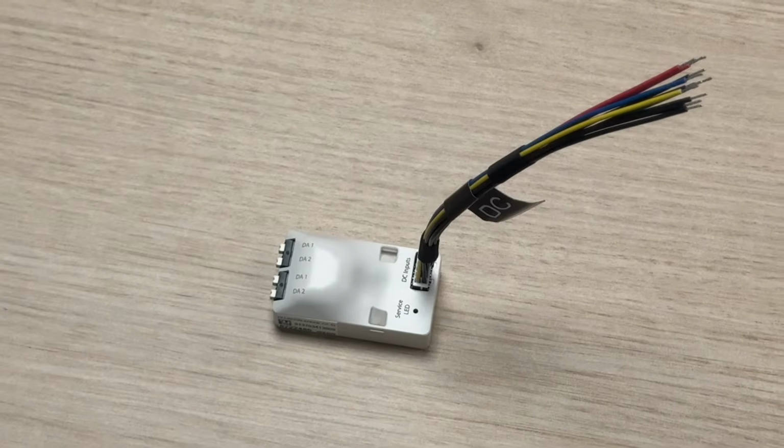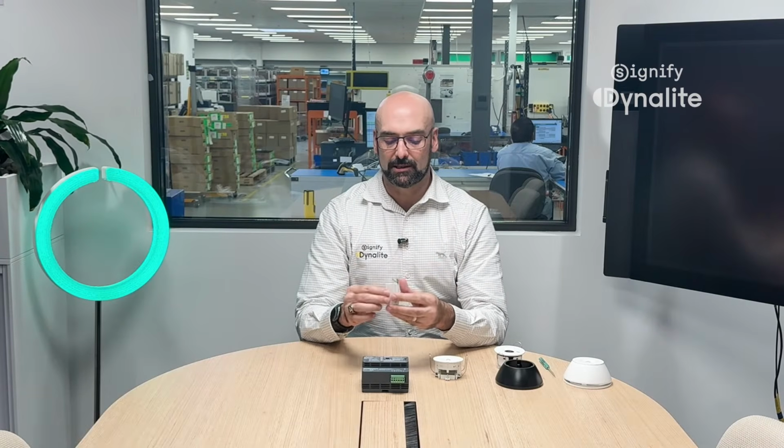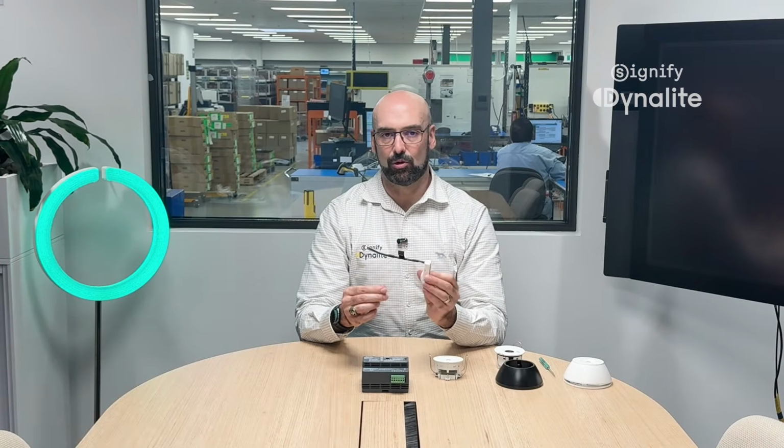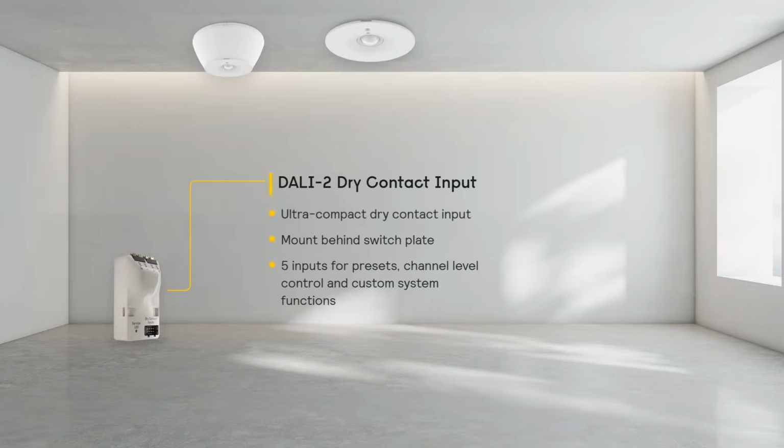Paired with this, we also have a new dry contact input interface. This is following the same mechanical design as we have for our Dynalite variant. With this here, it is meant to be able to sit inside a wall box, so we can cable tie it to the back and have our pluggable dry contact input interfaces straight to 5 switches. So the combination of a new DALI 2 sensor and dry contact input interface allows us to be able to fully spec the DALI 2 system and approach the multi-master requirements that our projects are looking for.